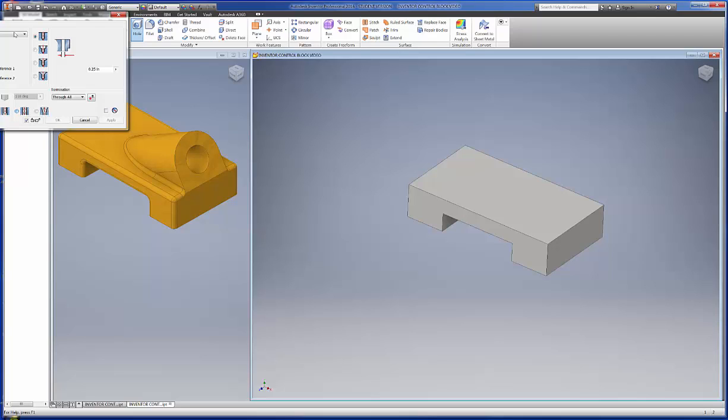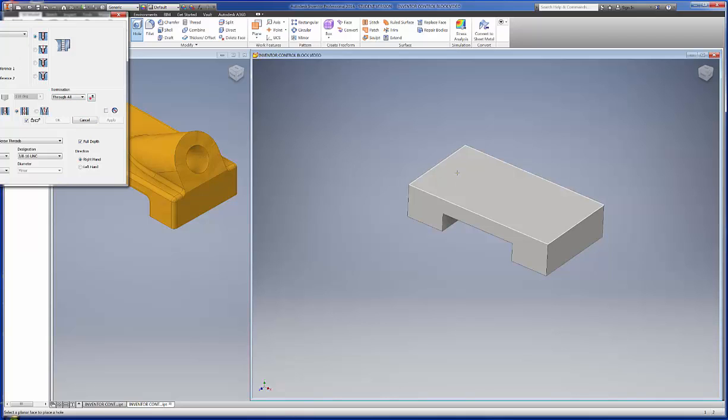And I apologize, my computer seems to be acting rather slow today. We should be able to get a hole here, and it should be threaded. It's also going to be linear, and we would want to select the faces and such, but we really need to, there we go. It is a unified screw thread. It is a 3/8-16, so we'll have to go here to 375, and there's your 3/8-16 2B. The thread goes full depth, and the hole goes all the way through. So we'll go ahead and pick the face, and we'll pick a location for that, and we'll right click.